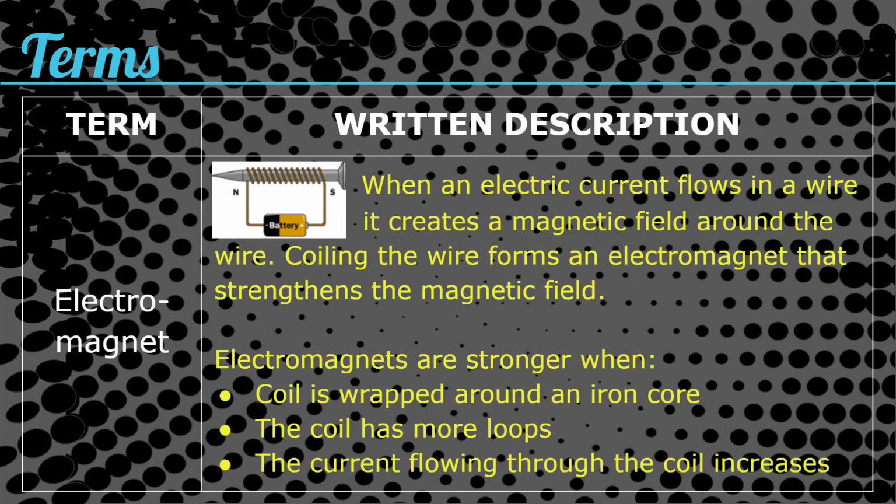If you put a nail or a bolt or just some kind of iron rod in the middle of your electromagnet, then now it's not just the field created by the current in the wire, but also that field is going to cause the domains to align in that material, and it's going to act more like a permanent magnet would.